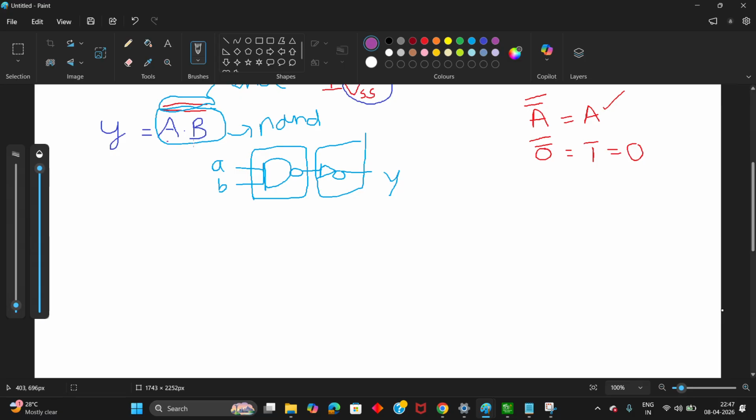Okay, we have known that we require two PMOS and two NMOS in the pull-up and pull-down network respectively. Now, how do those PMOS and NMOS need to be connected with each other? For that, you need to see the operation between the variables. If it is the product or the AND operation, then you should connect the PMOSs. You observe my wordings. I can't write over here because the video length will be very high. If you want the writing part also, I recommend you watch the NOT gate video. I will just tell you in an oral way.